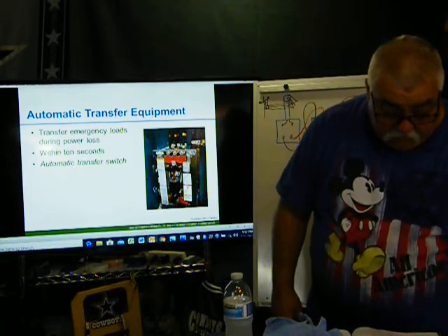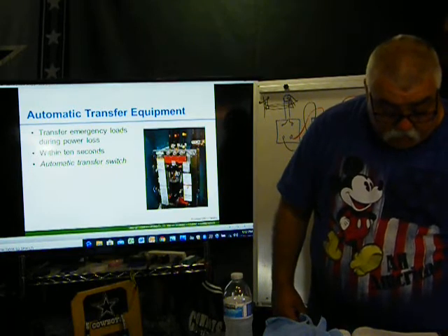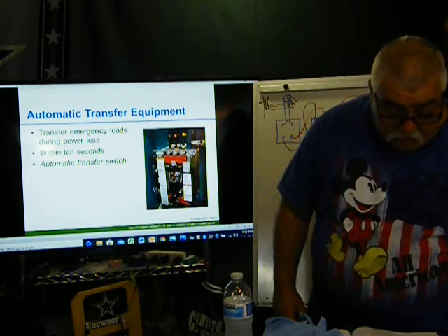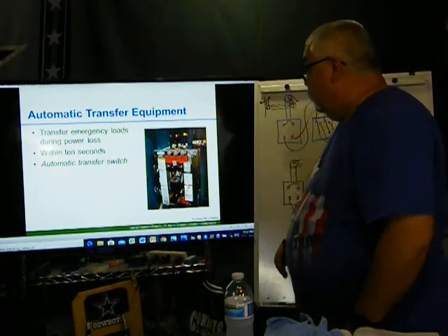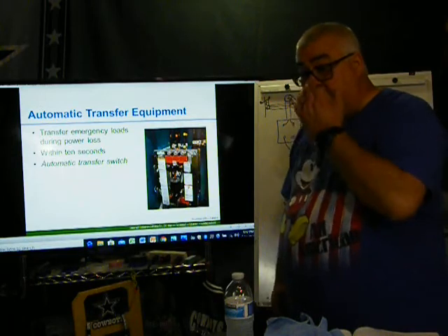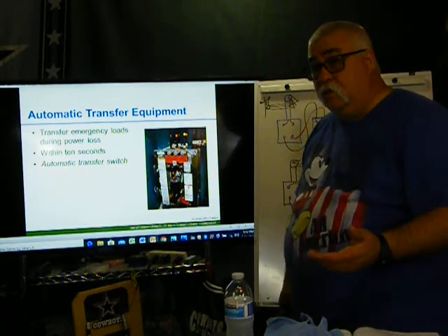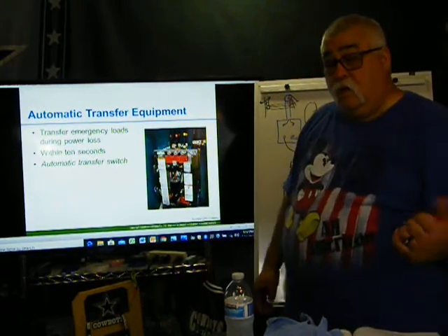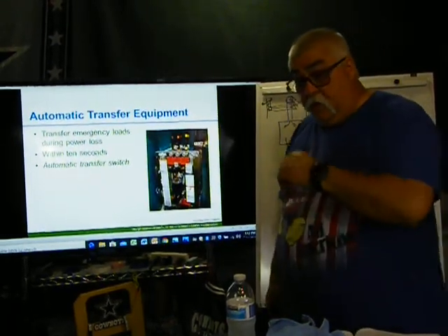When the standard power source supplies little or no voltage, the automatic transfer switch signals the generator supplying the emergency power. So this would transfer over. Sometimes they read current, sometimes current and voltage. This is always good because in case you have too low a voltage, this would also transfer in to allow the generator to come on.